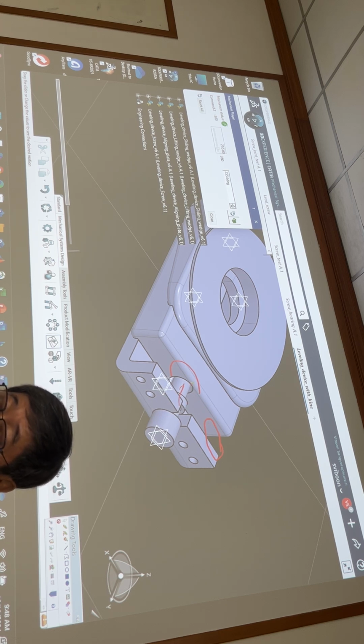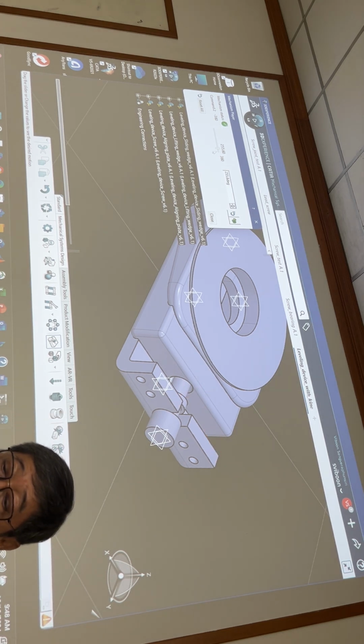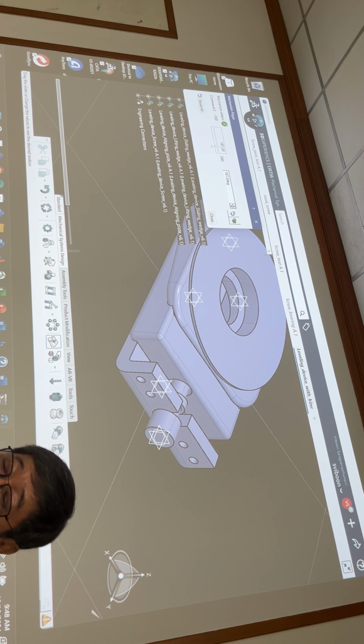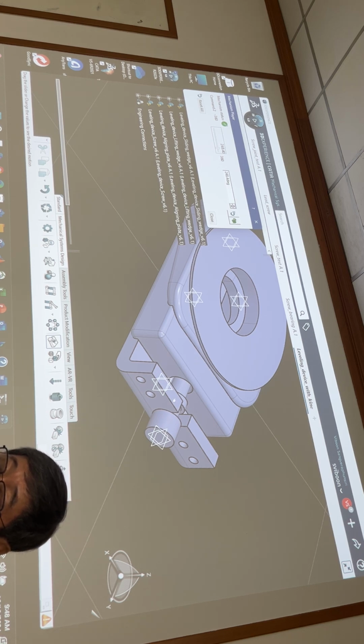Between this one and this one has to be a screw joint, because this rotates and this moves. If you rotate this knob, it moves this one, and you need to add a revolution screw joint between this link and this link.